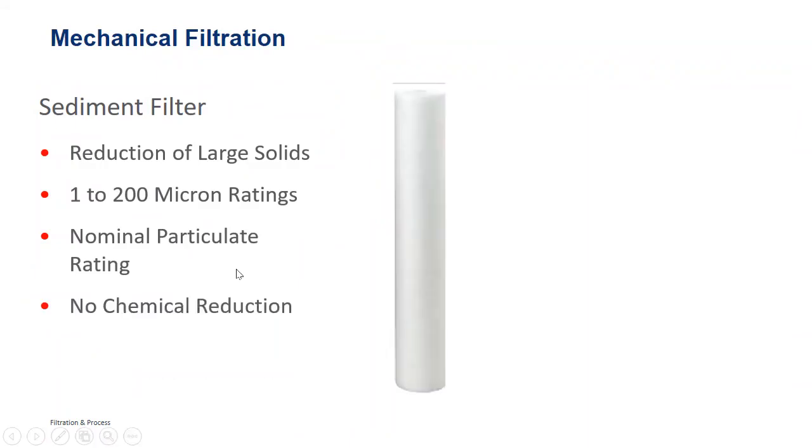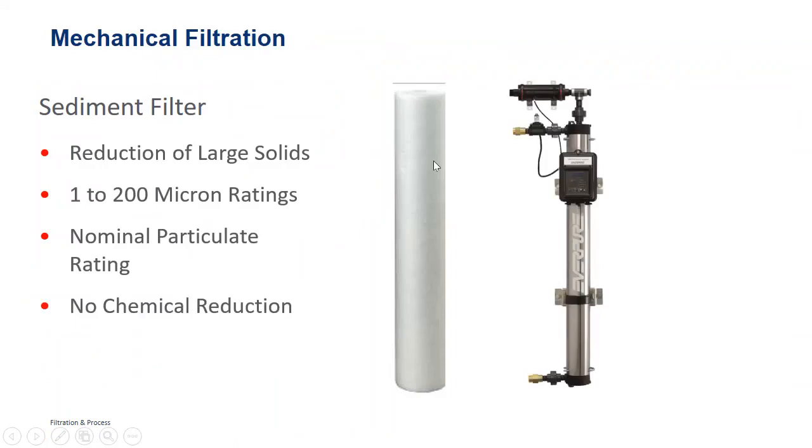And this does no chemical reduction. It may do some organic reduction. Why? Because some of these materials are synthetic organic fibers without a charge. This may attract some organics from the water, but that's not what it's trying to do. This is kind of like the Tupperware in your dishwasher that leaves that oily film on it, doesn't quite get it off because it's too tightly held to the plastic. That's the kind of effect with organics you'll get here, but they're not rated to do that. They're not designed to do that. This is for dirt loading.